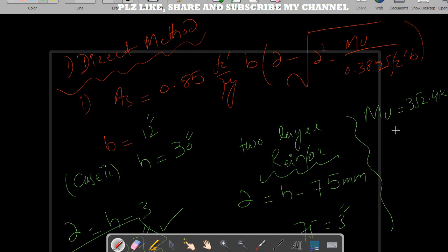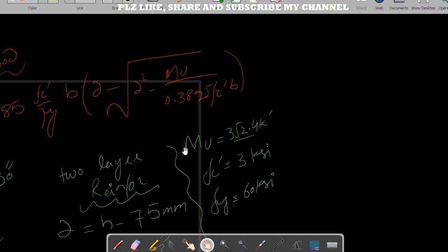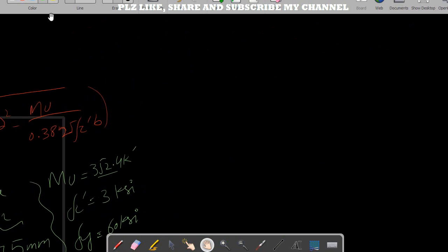This is kip-feet, so it must be multiplied by 12 to convert it into inch units. We know about fc prime, which is 3 ksi, and we know about the fy value, that is 60 ksi. So all values are in hand, so we will plug all the values and calculate the value of area of steel.